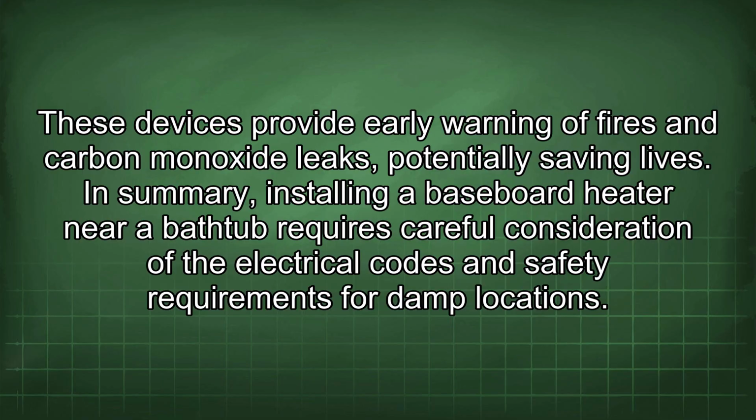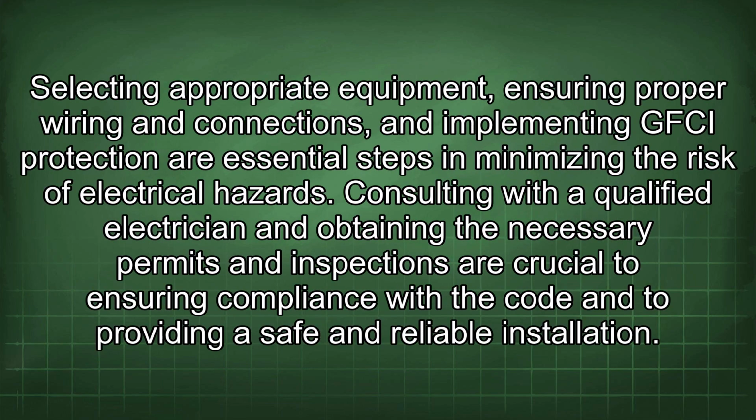In summary, installing a baseboard heater near a bathtub requires careful consideration of the electrical codes and safety requirements for damp locations. Selecting appropriate equipment, ensuring proper wiring and connections, and implementing GFCI protection are essential steps in minimizing the risk of electrical hazard. Consulting with a qualified electrician and obtaining the necessary permits and inspections are crucial to ensuring compliance with the code and to providing a safe and reliable installation.